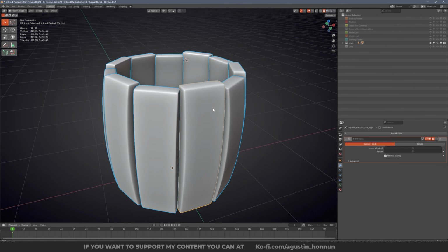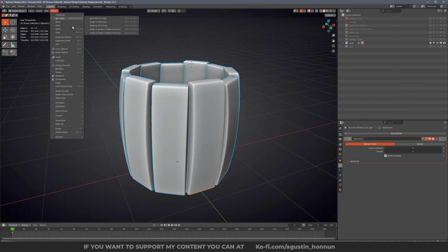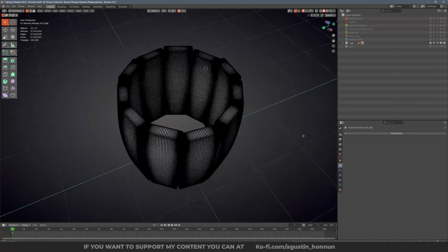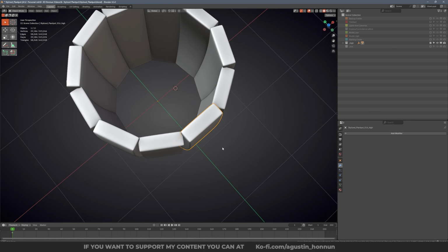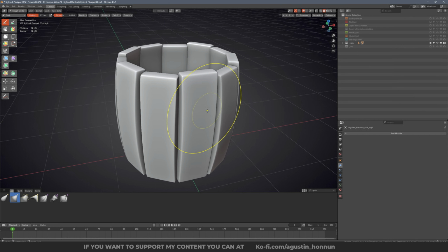Yeah. So select everything and press convert to mesh with Alt-C, or go to object, convert, mesh. Now all of this is a real mesh with no modifiers. Now select everything, apply scale, and go to object, sculpt mode, and here you need to press Shift R or Control R and select an amount here, something that your PC can handle, or go here to remesh and use the voxel size and type something like this. Don't go too low or Blender can crash, and remesh.